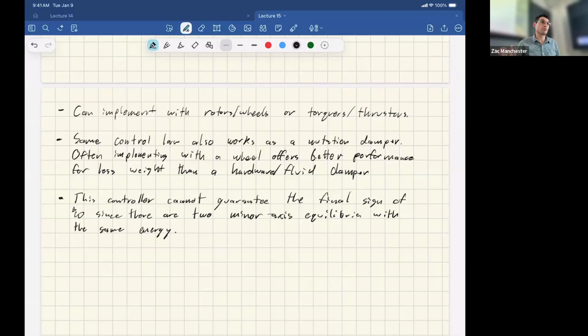Well, they can be positive or negative, at least in the wheel case, not in the thruster case. So minimum absolute value. That's an L1 norm, and that will actually produce the maximally sparse solution. So that'll tend to make a bunch of them zero. If I had the JPL configuration and I did that, it would basically always zero out this fourth one and always use the other three. So it's not quite what you want. Any other ideas? But it's a good instinct.